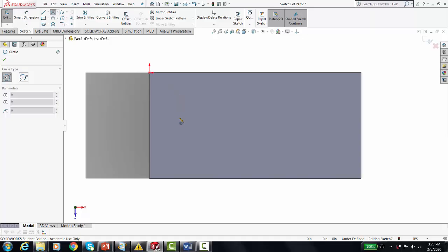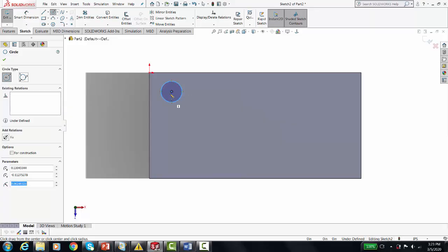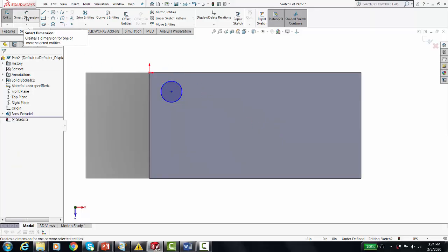If I change the width of the block, it's going to expand down to the bottom of the screen and to the right because I have it fixed to the origin. So I'm going to draw my bump over here so I can create a pattern that goes down and to the right. So as I change my part, hopefully that pattern has room to expand in the same direction as my block. So that's the design intent.